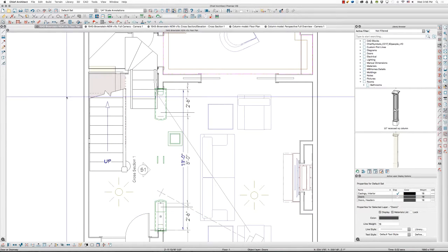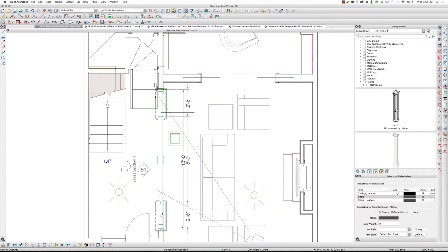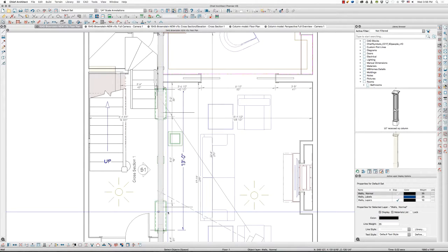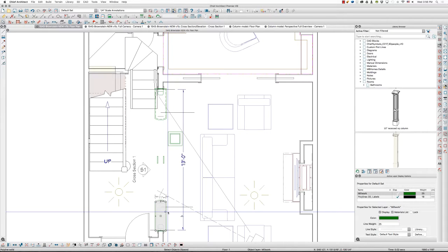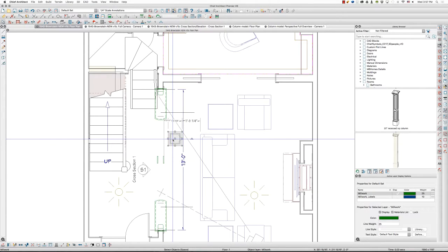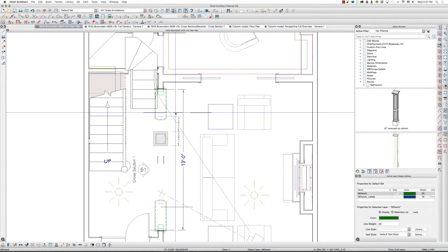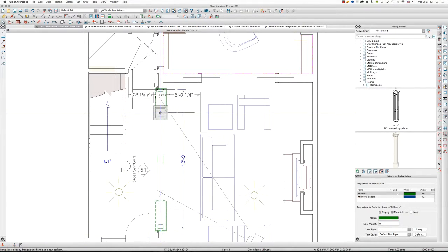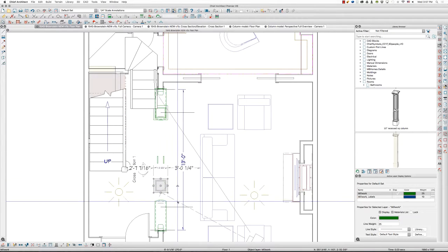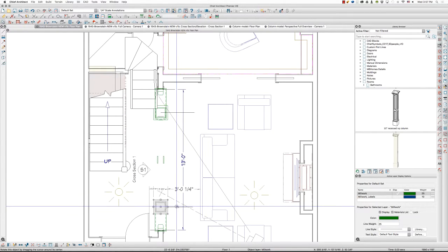So what I'm doing is I'm in the select mode. I click once, it's selecting a doorway, tab on my keyboard, that selects the wall, tab again, not it, not it, not it. Okay, I gotta select again closer. There we go. There's the millwork. Now, I've got my column. I'm gonna Command G, center about this wall. Command G again, center about that line. Copy this piece. Drag it over here, Command G, centered about this line.